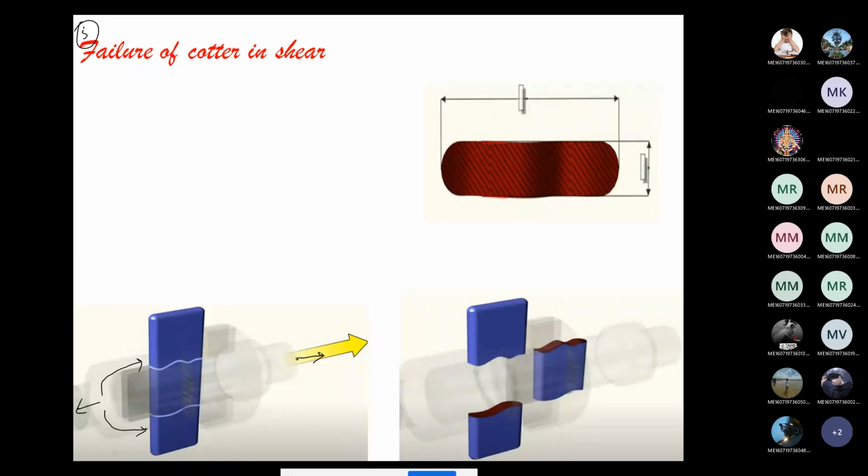and on the spigot we are applying the load. This load is going to appear here. Okay, so this is the first image. That's the reason half of the portion is carried along the socket, and the middle portion is carried by the spigot. So in the second image you can see the top portion and the third portion coming along the socket, and the second portion is coming outside from the spigot, right?